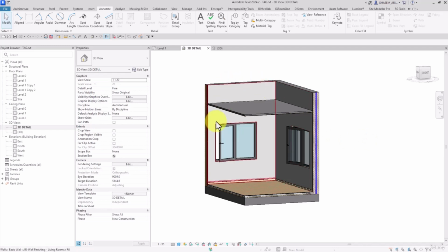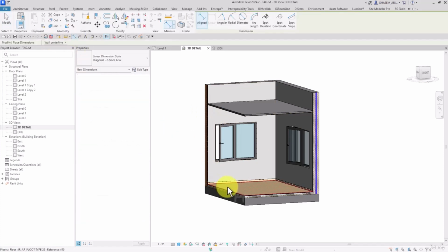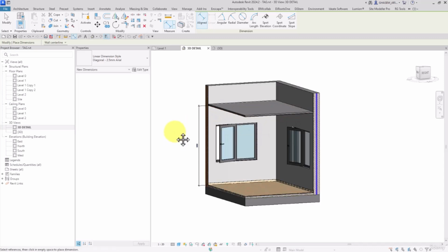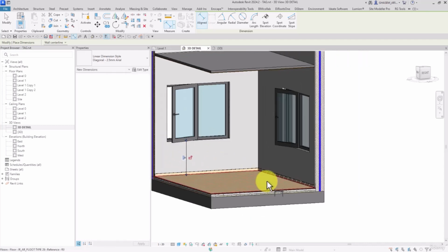And a point about the 3D views, I should say that you have to lock the view orientation before adding the dimension lines. And you have to set the work planes. For instance, pick a plane. I set it on the wall face. Then I use the dimension lines for the height, for instance, in 3D view. Like this way, the sill height.